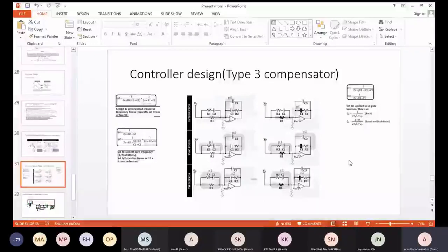So this is the diagram of a type 3 compensator. Whatever is shown here, you can see that 100% PID can be implemented. The shaded portions on the left-hand side indicate the kind of poles and zeros that these things are incorporating. Basically, this type 3 compensator is incorporating many things. How to incorporate them, and what the values of these things are, is what the design is about.